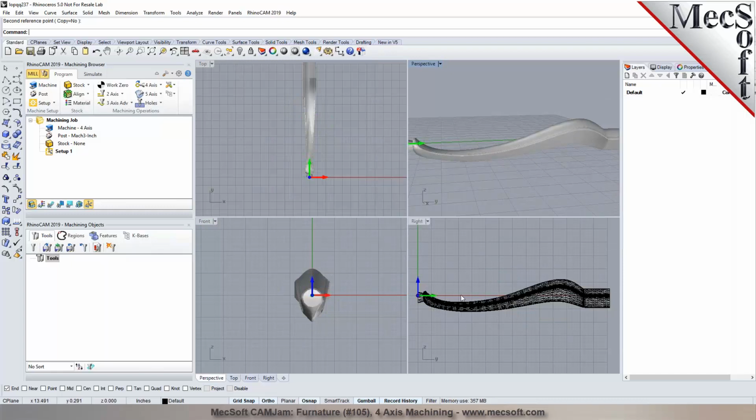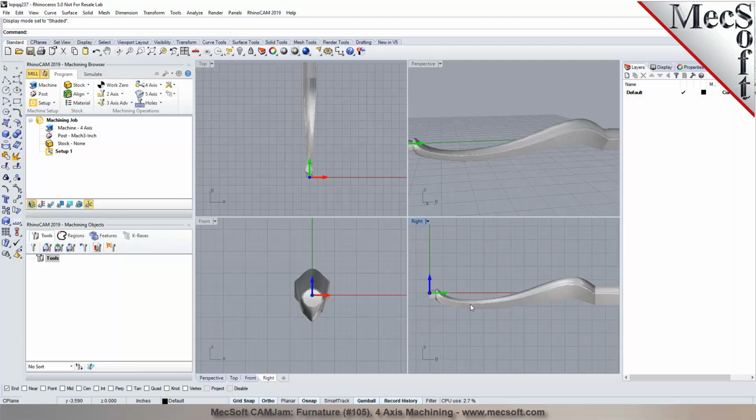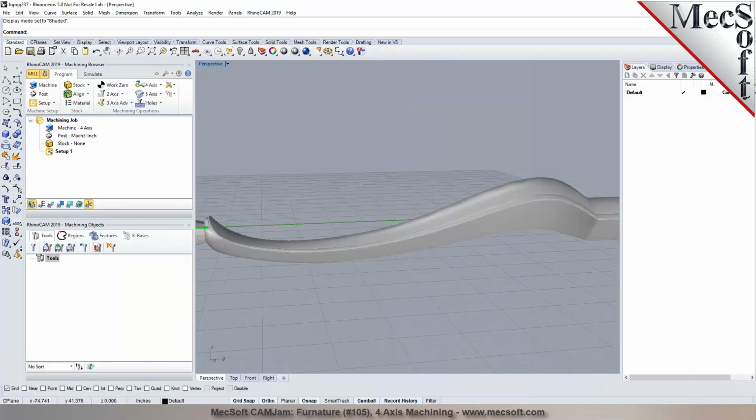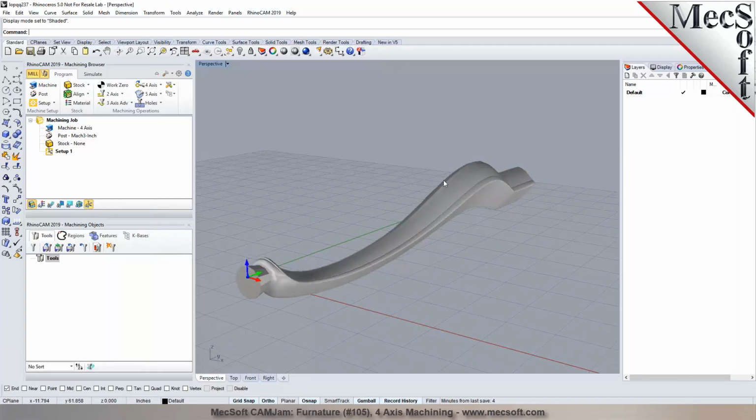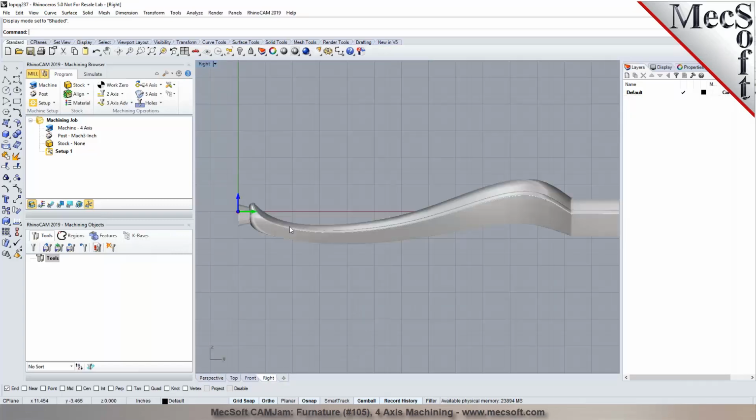So you can see this undercut if you look at it from the right side view. Yes. So when we do our 4-axis machining operations, if you do a 4-axis parallel finishing, which is one of the methods, it's more like a projection type of method where the tool will not let you dip below the rotation center because the tool remains normal to the axis of rotation, so it's not going to dip below this. Now, just for programming this section here, we can actually do an indexed operation just for this area.